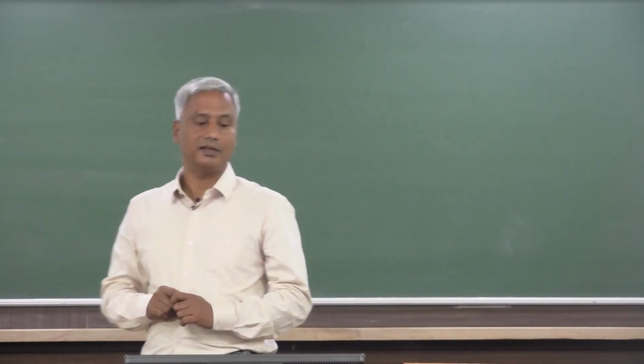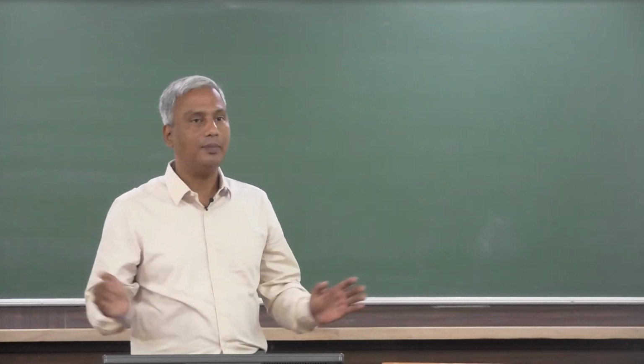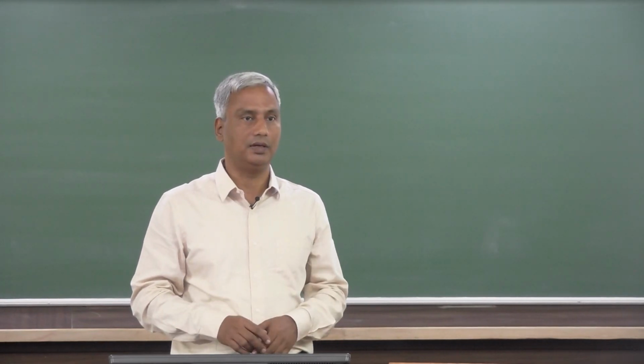So, what will you do in that case? I will increase the cross sectional area of the conductor. As soon as I increase the cross sectional area of the conductor in such a way that my overall resistance comes down, then I will go not even to a milliwatt, maybe microwatt, and then my energy consumption because of the heating of the bus bar will reduce. Heating is nothing but waste. You cannot utilize that energy anywhere. Or I will reduce the current. In both ways, I will be able to reduce my wastage of energy.